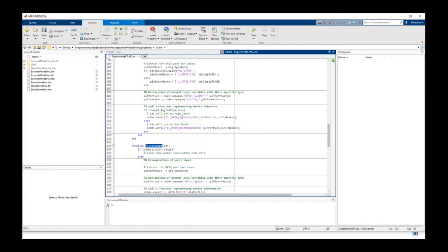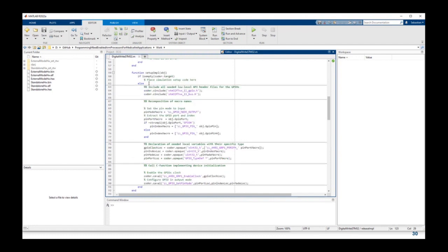Now if we take a look at the code, for example, for this initialize function, you can see that you can parameterize your system object so that it can work in simulation mode. Here, if I'm not using code generation, I could provide a functionality to this block. Here I did nothing, but it is possible to do what we call the IO mode, which is something new since 2 or 3 releases, which allows you to bring data from a real hardware peripheral into Simulink for the simulation. This is what is called the IO mode.